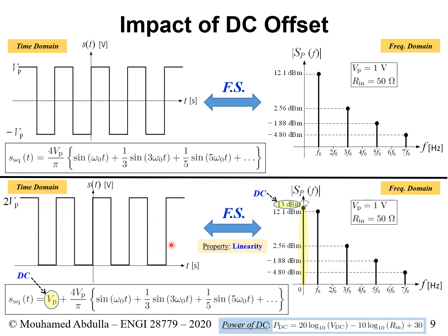The only case where you know for sure there is no DC component is when the signal, looked at in the time domain, is odd. You know for a fact there is no DC component. In all the other cases, it is possible to have a DC component. It doesn't mean it's always there, but it is possible. There are cases where you have an even signal and there is no DC component, so you really have to inspect it to see that. But that gives you another hint for visualizing DC in the time domain.